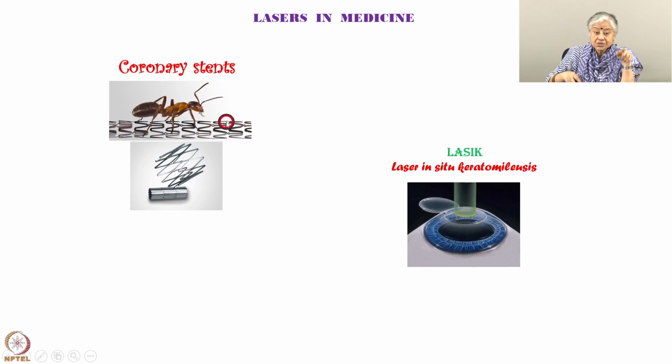So again you have to choose the laser wavelength very well, you have to choose your focusing optics well, and whether it will be a pulsed laser, what is the duration of the pulse will determine how fine and clean this kind of a cut is.